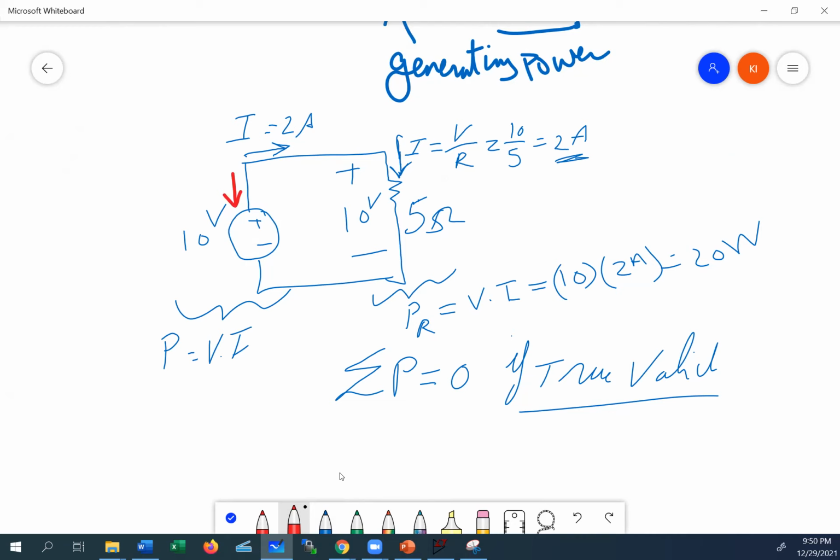If I'm going to use P equal to V times I, I have to have my current coming in to this. So the way we draw this is, when you have the opposite arrow, you have to make it a minus, so you can still keep the actual current going the other way. This is mathematically showing it going in, but the -2 says it's really not going in, it's going the other way. So V times I would be 10 times -2, which says power is -20.